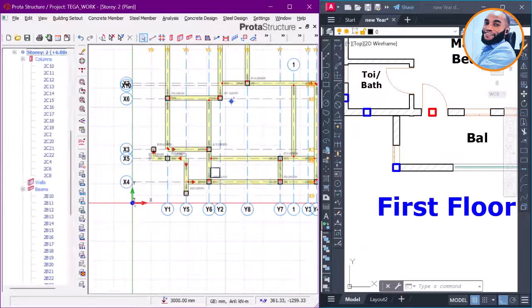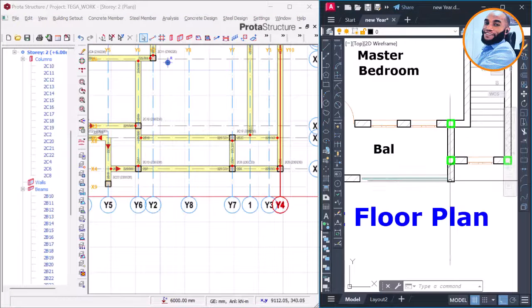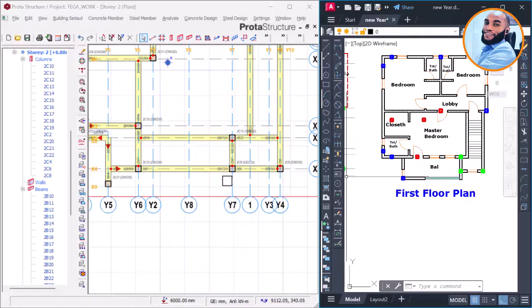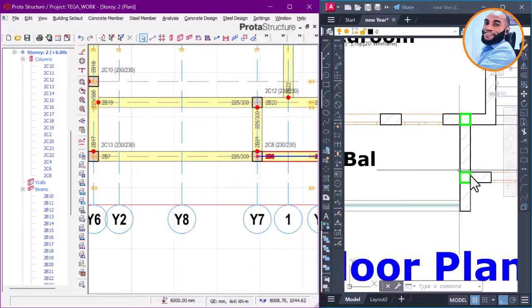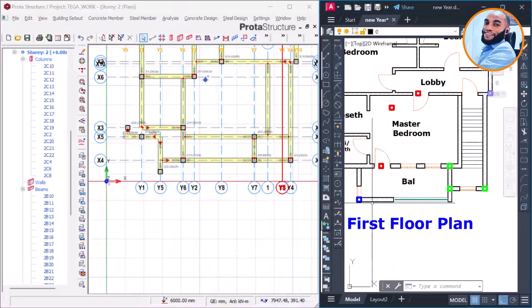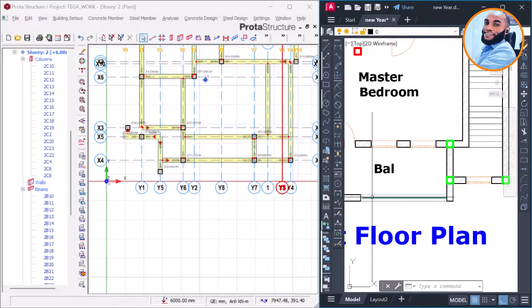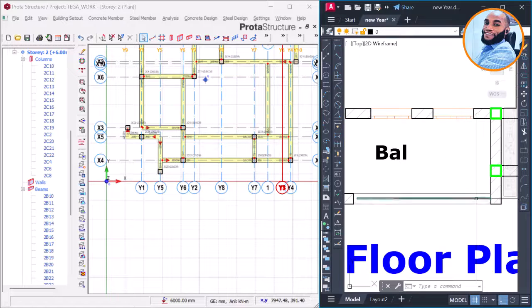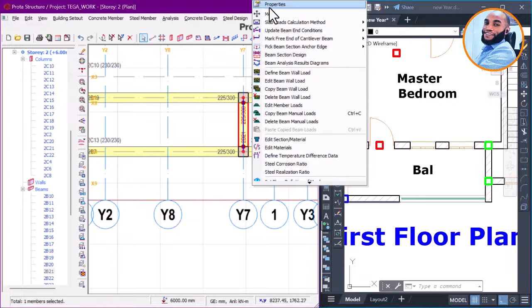We'll just bring this one out, and then throw a beam. This column here is not meant to go out because it's still hiding inside the wall, but I don't want this length of wall to stay without a column at the edge here. Although it can carry without any crack, because here is already an opening and like an arc, so we can do that. So right now, instead of putting a column here, we just do a cantilever beam out,